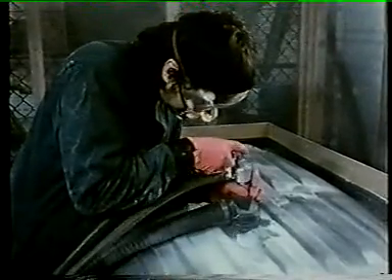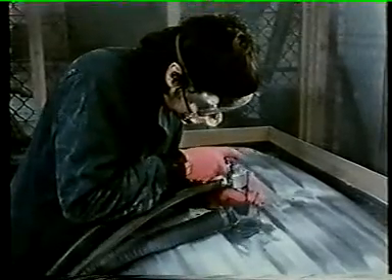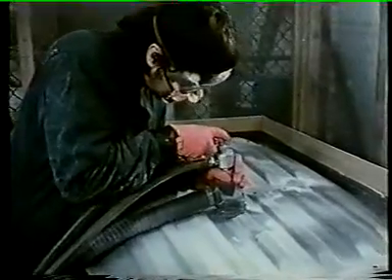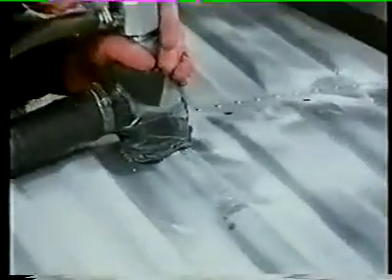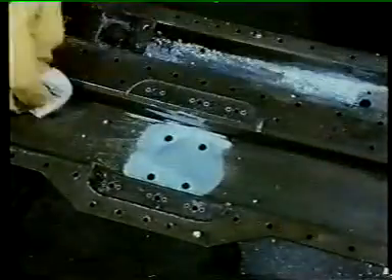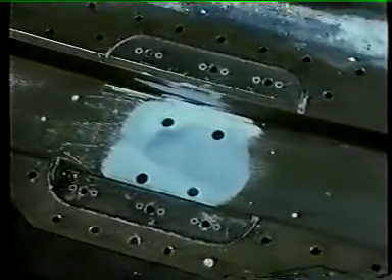Rectification is usually accomplished by either cutting away the affected area or by abrasive blasting with a stream of fine alumina grit. This scours away the corrosion products, leaving a clean, dry metal surface. Chemical treatment is then required, but it's necessary to ensure that all the reagents have been removed afterwards.